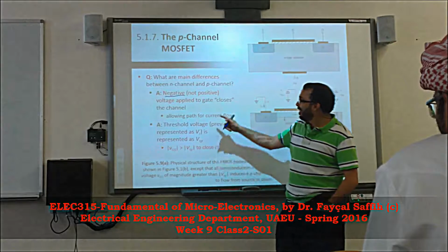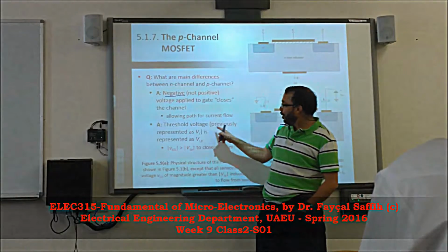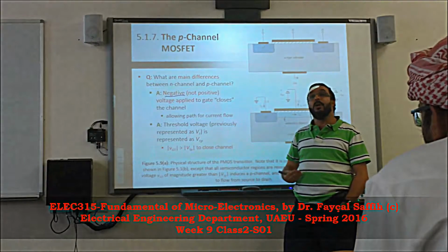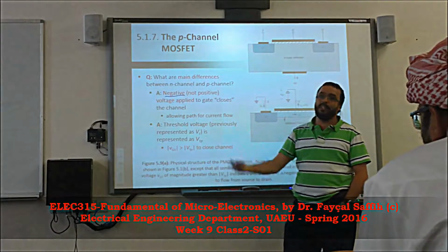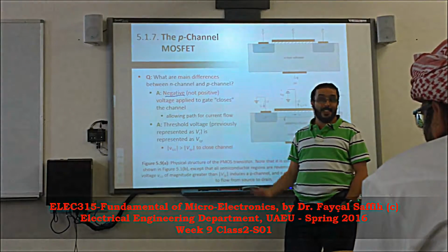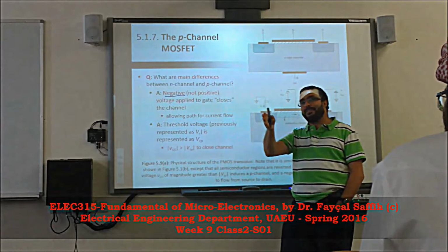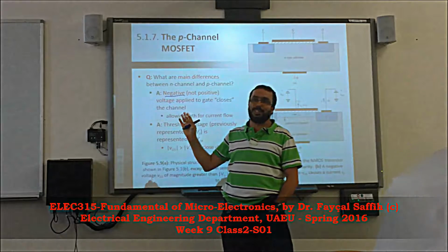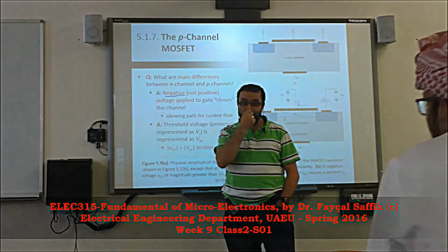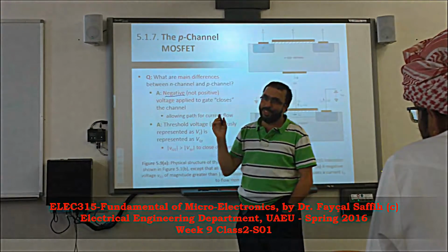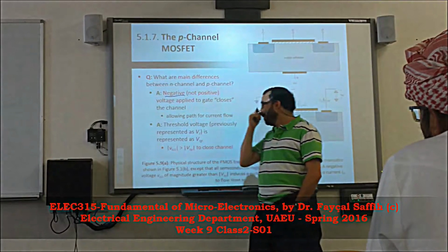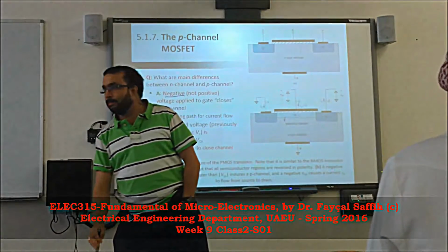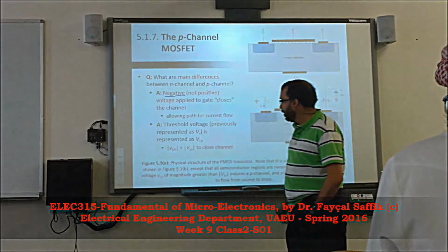That's what it is. So now the threshold voltage has to be negative for the PMOS, because we need to be more negative at the gate to create a channel. So it's the opposite. I told you, look at the mirror, you will see the other side. As simple as that. It's a beauty. It's amazing how this happens. But this is nature. We didn't do anything, we just studied it. Got it? Bilal? Clear? Very good. Ali? Yes?